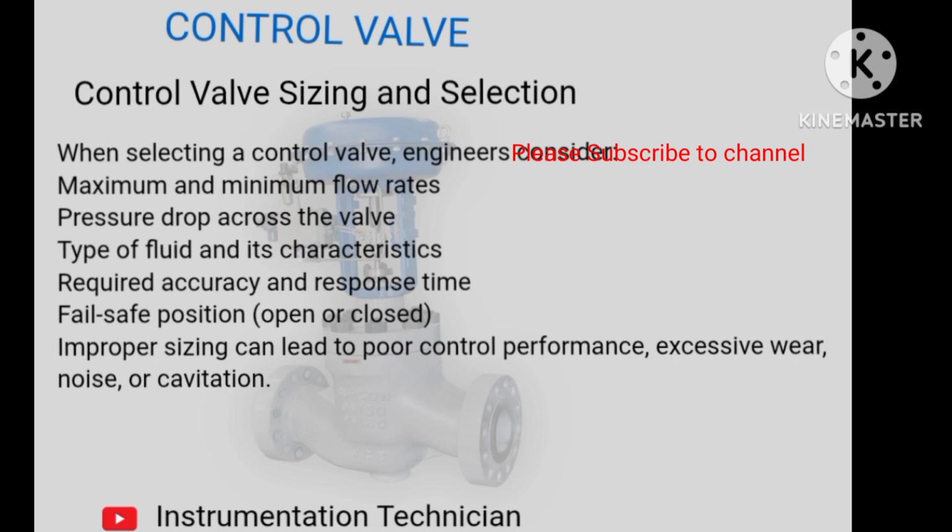Control valve sizing and selection. When selecting a control valve, engineers consider maximum and minimum flow rates, pressure drop across the valve, type of fluid and its characteristics, required accuracy and response time, and fail-safe position, open or closed. Improper sizing can lead to poor control performance, excessive wear, noise, or cavitation.